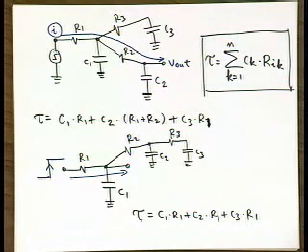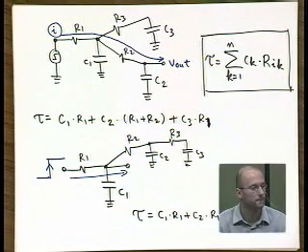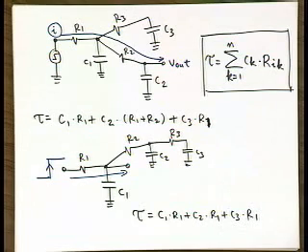Okay. Another question. So now suppose I want to discharge, and so my output is an opposite, meaning a high to low transition at the output. So now if I just look at the time that it takes to discharge only C1, then it will be just R1 times C1. Oh, that's a really good question.